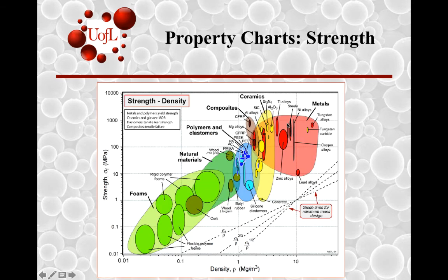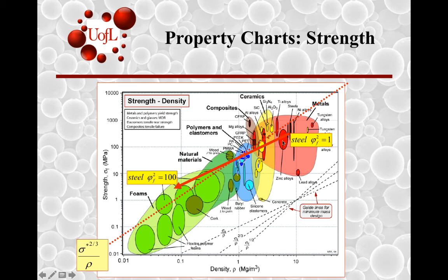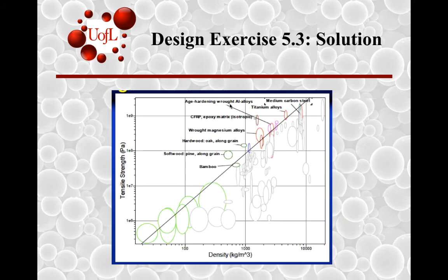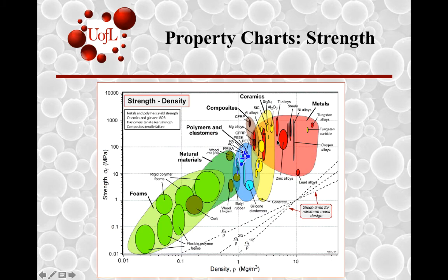and the fact that you could go from a steel that was poorly shaped to a steel that was more effectively shaped into a useful structure, to move it from something that was completely out of the reckoning to something that was more competitive. And then similarly for aluminum and so on, and carbon fiber reinforced plastics will be right there anyway. So you get a chance to see how, based on shape efficiency factor differences, CFRP was very close, but as you increased or varied the shape, you could end up getting a better choice.